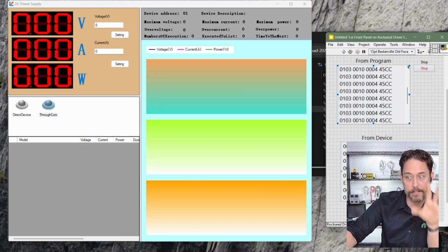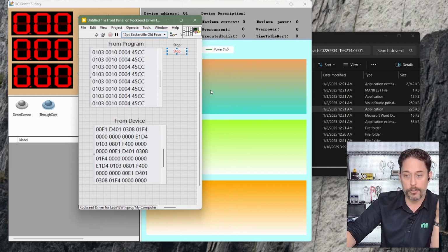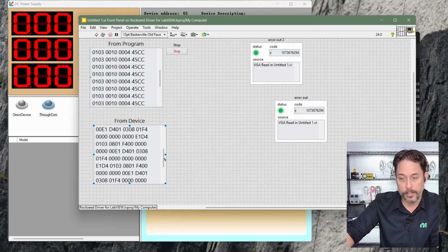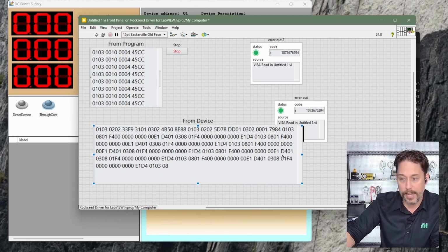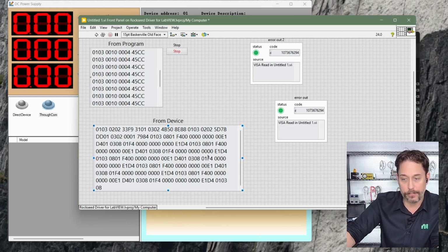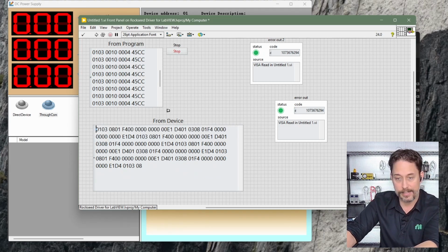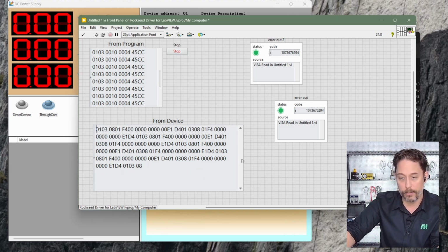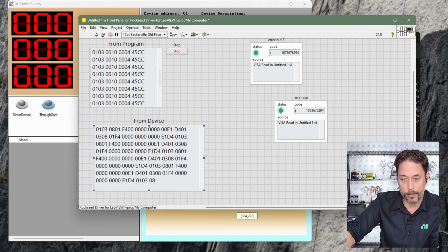Once again, we're leveraging the environment, the language and the features to do a little bit of reverse engineering here. So let's stretch out that data. And remember, we said that there was a bit of a repeating pattern in terms of querying probably its current status, so we would expect to find a repeating pattern down here. We're also going to look for that 0103 pattern, because that's probably the response that we're looking for. And actually, there's one right there. Let's trim off the data ahead of time, and we can start to figure out, hey, where is our repeating pattern in our overall program?